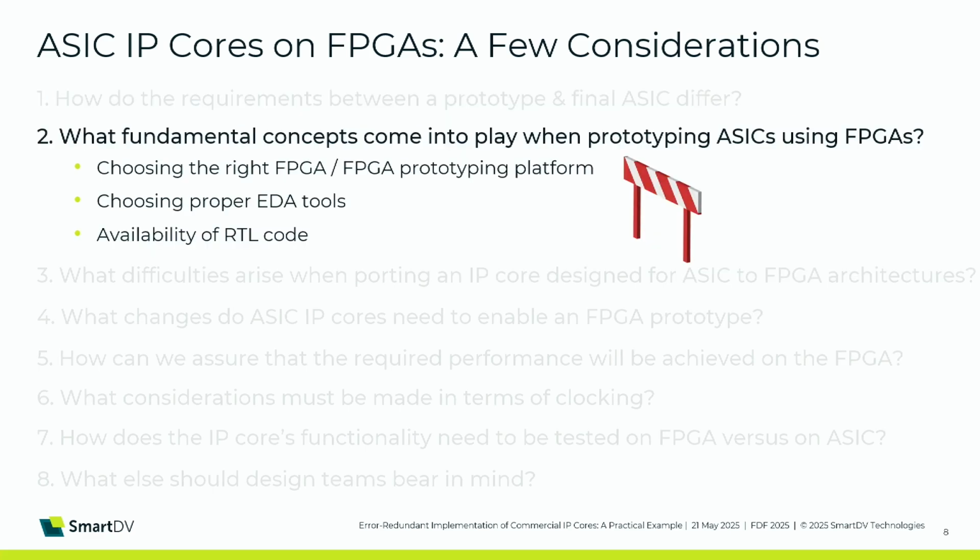Okay. Then the next topic to discuss is when porting such an FPGA IP core, we need to understand which FPGA or which FPGA platform to deploy. Let's make a practical example here. So given the fact you want to import a PCIe core Gen 5, Gen 6, okay? Now you have to choose a proper FPGA. So obviously this would not be a low-cost FPGA from any vendor because you could expect timing and also area issues.